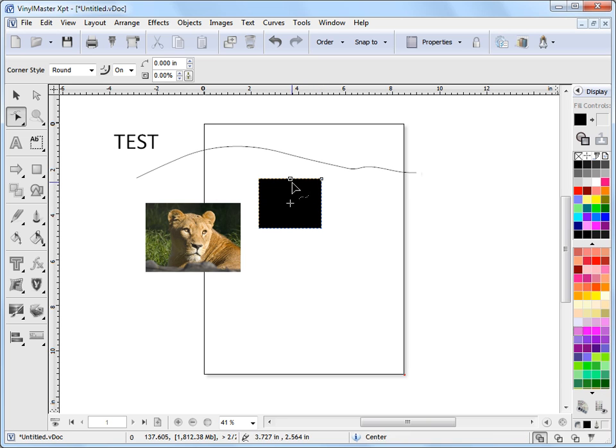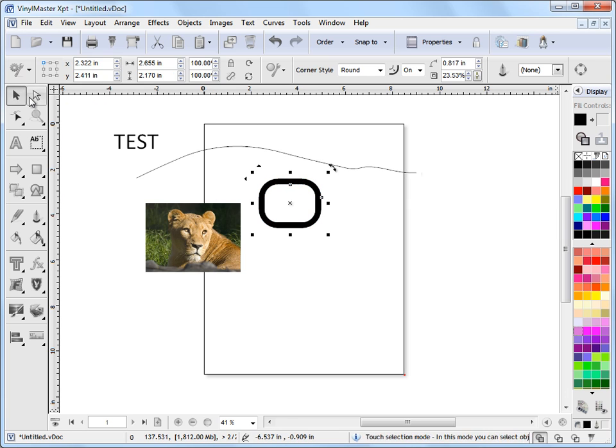They're a different type of node. So as you can see here, I can change the corner style or the border thickness. These are node controls I've got, but it's a different set of tools, and as you can see in the second row, it automatically recognizes that, and I see a different tool set. Okay? If I go back into object mode, I get all my square tools here.